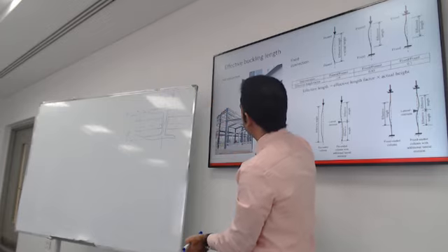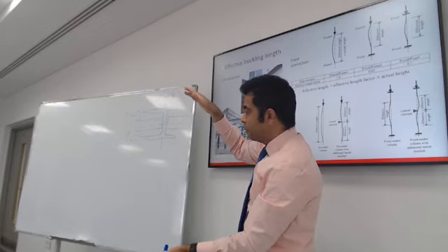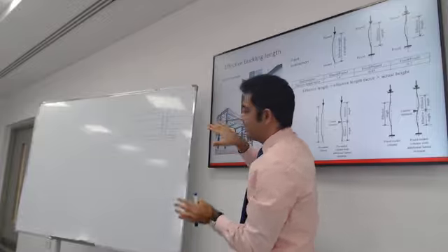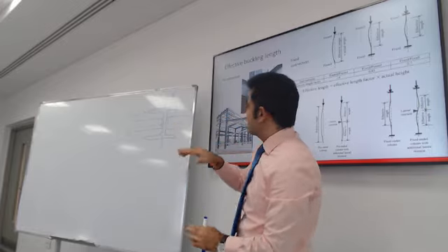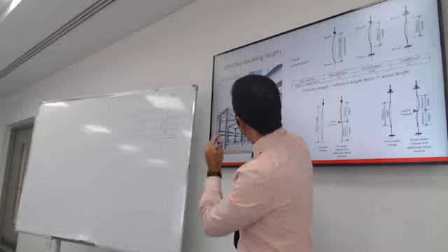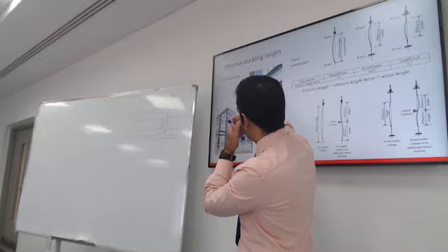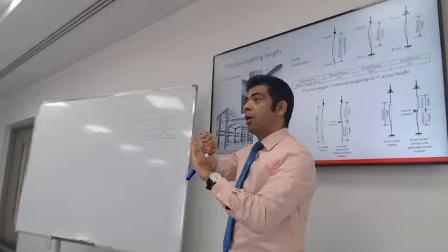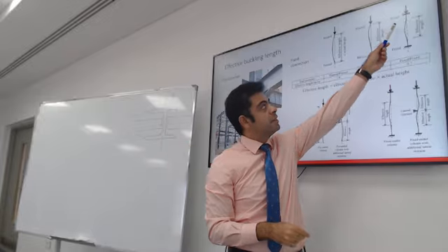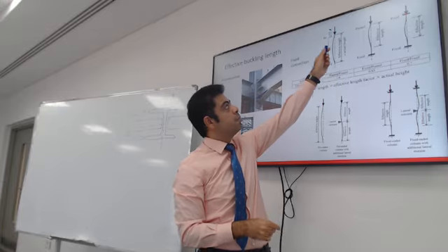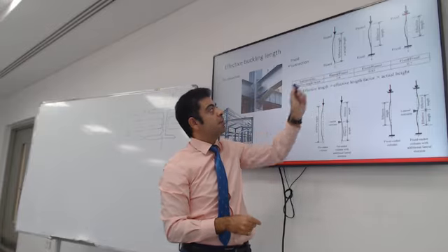There are additional stiffeners all welded to this plate, and the plate is bolted to the column. This connection is fixed, so that will affect the laterally unsupported length for the beam and for the column as well. A column that is fixed with a beam will have a fixity condition. If it's pinned with the beam, it has a pin condition.